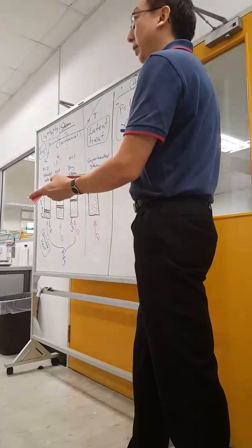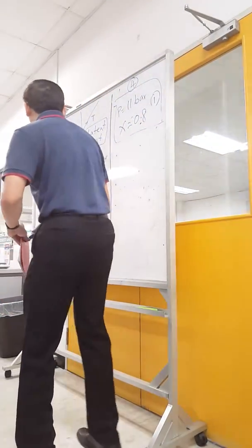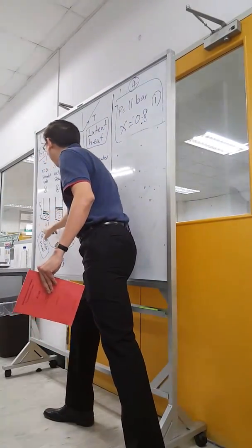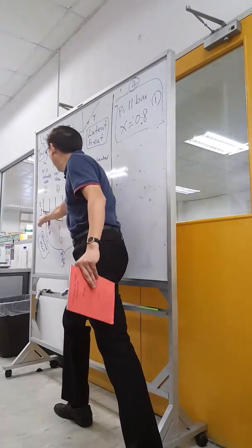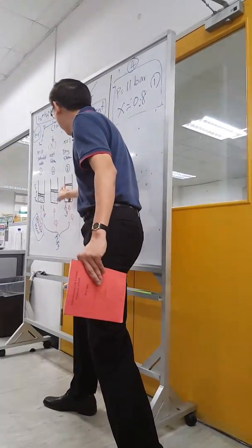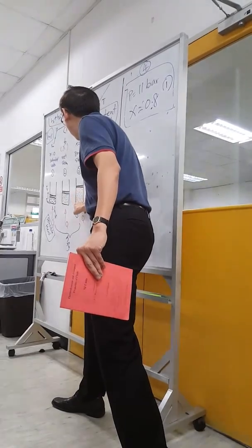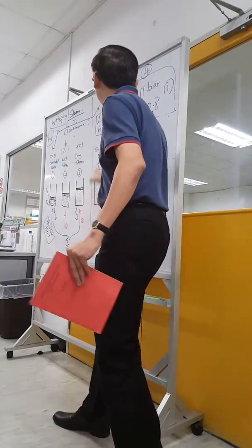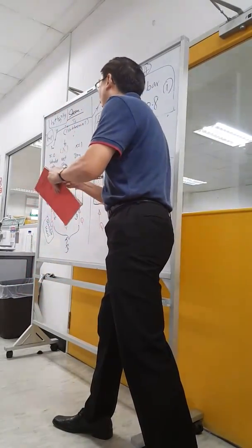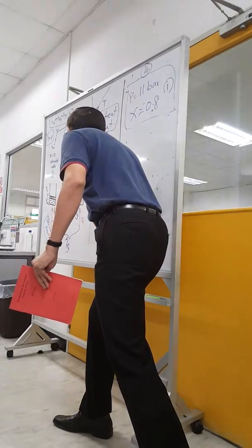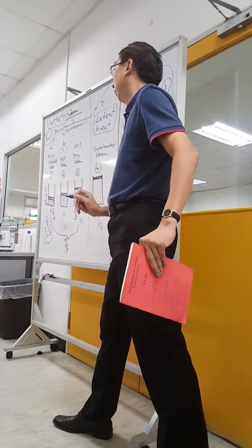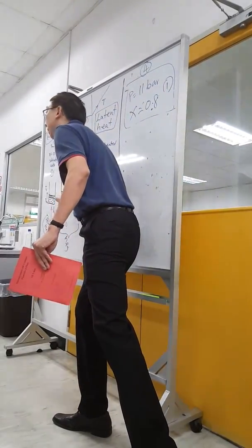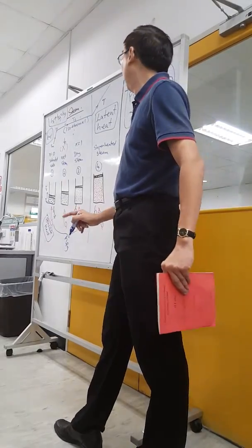Okay now, so how to find it? Look here. The last thing I need to tell you is that at stage 1, the total energy is Hf. At stage 3, the energy of this steam is Hg. And at superheat, the term given is just H, H for superheat. What is the total amount of energy inside here? Hg minus Hf. This is x.